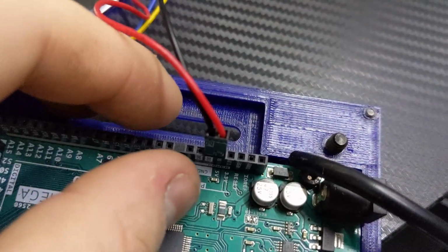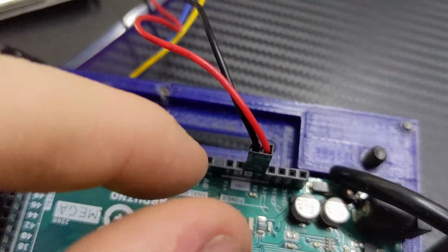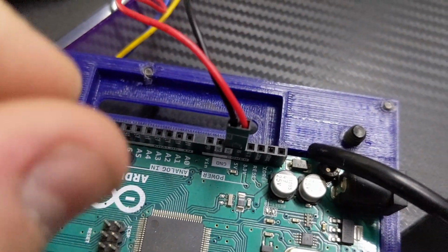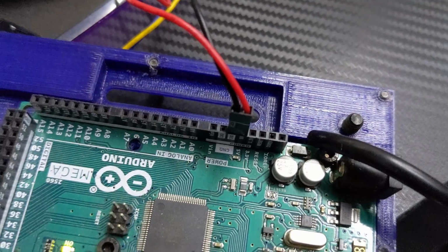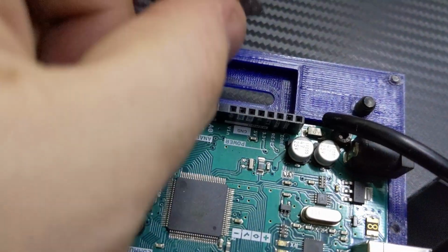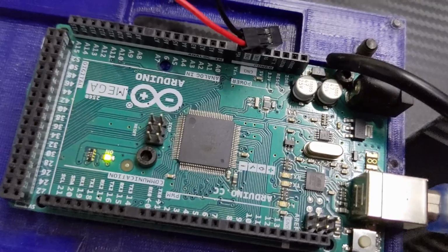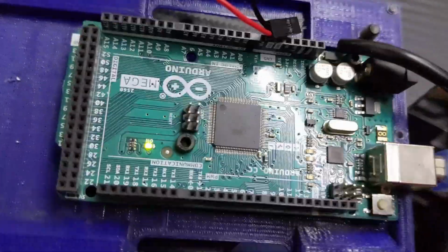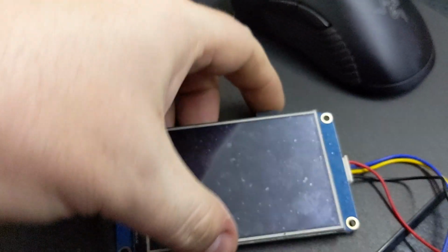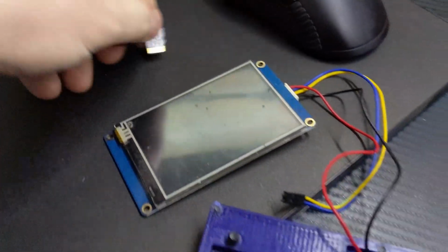Okay, now let's unplug it and remove the SD card. Be careful, don't unplug it and plug it back in accidentally. You want to commit to the unplug, just pull. Because it'll try to load the firmware again if you cycle the power like that. So, boom. And I like to unplug it like that rather than shutting down the Arduino because there's some capacitors in here that take a little while to die. So, remove the SD card. And our firmware should be loaded now.